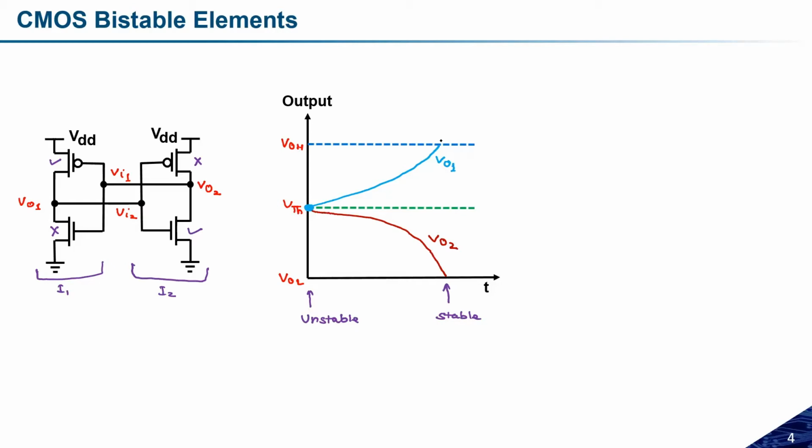So one of the outputs will store logic 1, and the second output will store logic 0. This is how forcefully we can store the data in memory. This is the basic building block to create the static random access memory.